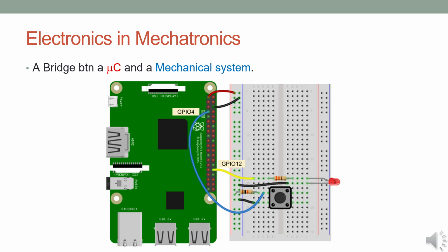The Raspberry Pi offers two main types of connections: a 40-pin GPIO header for general purpose I/O, and communication ports such as USB and Ethernet. For more complex data transfer, we'll focus today on the GPIO header. In the demonstration, GPIO pin 4 is connected with a blue wire to a push button, allowing the Raspberry Pi to receive input. Meanwhile, GPIO pin 12 is connected with a yellow wire to an LED, allowing the Pi to control output by switching the light on and off.